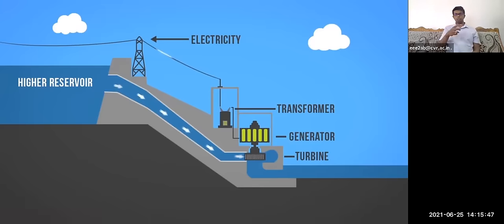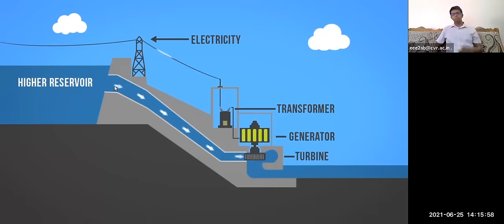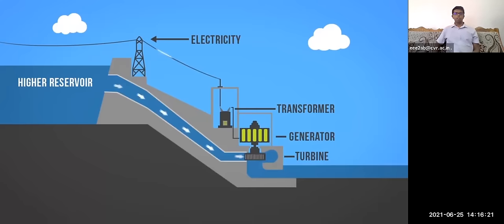As we have seen in the previous video, if you open the gate, water will flow to that penstock. So a series of penstocks might be there. Today if we want 500 megawatt, and this generator is 100 megawatt, then you should turn on 5 penstocks. They turn on only the penstocks and sluice gates whose generators are in good operating condition, for a particular time, 5 hours, 8 hours, or 10 hours, depending on the demand, and they generate the power.